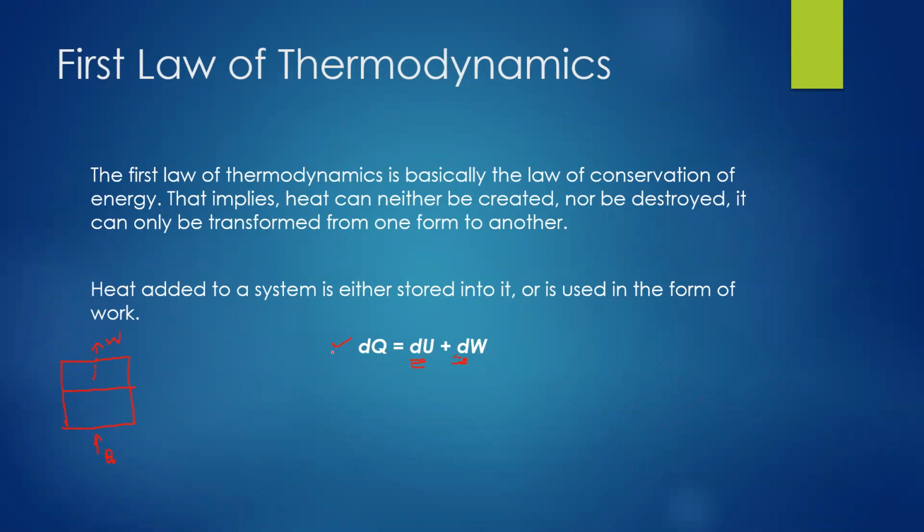This is the statement for the first law of thermodynamics. It gives you a specific statement for energy balance: dQ, heat added, is equal to dU, energy stored, plus dW, work done. Remember, work out is positive, work in is negative, heat out is negative, and heat in is positive. So the sign convention always needs to be kept in mind.